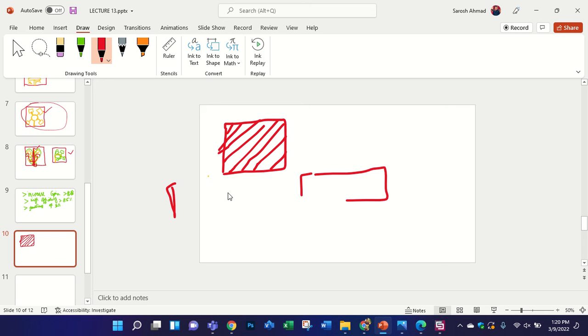But if you use the CPW technique, then you cannot achieve such a high gain. So in the case of the metamaterial, as I told you previously, maybe I will explain further. In the metamaterial you cannot use a full ground plane, because if you use a full ground plane, there will be no effect of the metamaterial, and then the metamaterial will be useless.